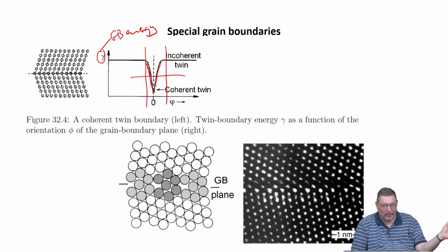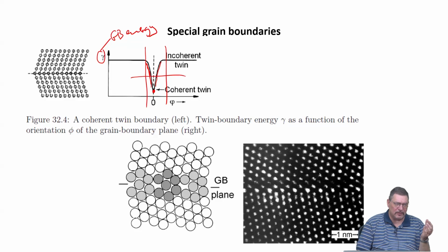And overall, maybe doing an analysis of the whole microstructure like you do in EBSD, where you press a button and you get the number fraction of CSL boundaries, will not give you a good answer. So maybe it's a good way to check some and see, because it would depend also on whether a twin boundary has been generated as a deformation-induced twin or whether it's a grown-in twin. The grown-in twins tend to have lower excess energy, so they are more like the coherent twin.